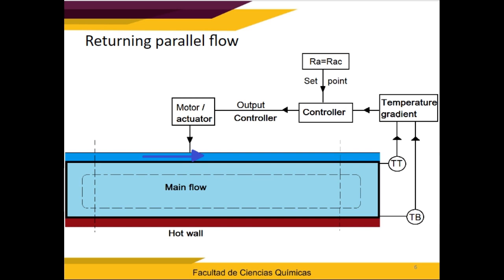At the same time, the bottom wall is heated so that convection is affected by the returning flow, also called principal flow. Around the cavity outside is shown a possible experimental arrangement for the measurement of temperature and further adjustment of the top wall motion in response to these measurements as in a feedback control loop.